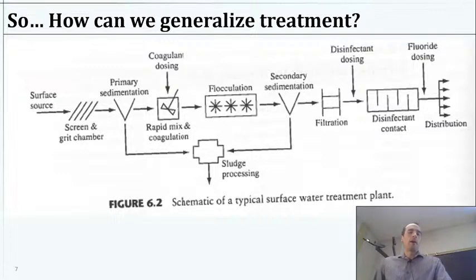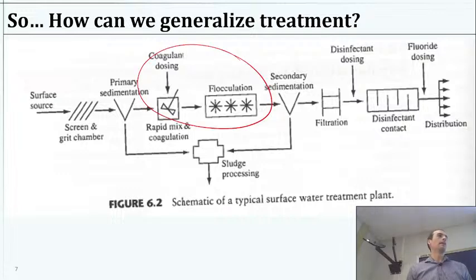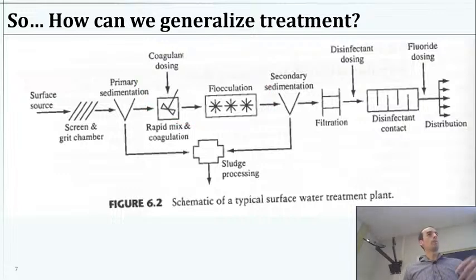Okay, so as we think about a typical treatment process, really what we're going to do in this class is dissect what would normally be a typical centralized system and say, well, how do we take that apart and just use what we need for a particular scenario? Maybe we're dealing with surface water. And with surface water, one thing you can do is some coagulation and let it settle. And you could do that in like a bucket type of thing. So sometimes we'll talk about some smart coagulation flocculation systems where you really just add a bit of stuff, stir it around, and then let it sit for a day, and then gently pour it into another bucket, and you have some sludge left over on the one. You could also add a bit of chlorine with that and do both at the same time.